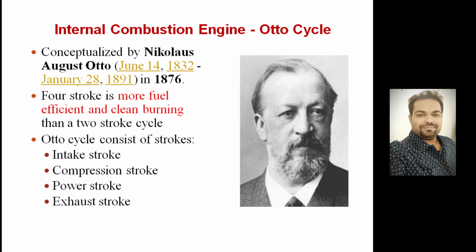The moment your piston is moving down, the piston is connected to the crankshaft with the help of a connecting rod, and the crankshaft will rotate and you will get the mechanical work. Once you have got the mechanical work, the exhaust valve will open. Once the exhaust valve opens, combustible gases will start flowing out of the exhaust valve, and pressure decreases inside the cylinder. Because of that, the piston moves from bottom dead center towards the top dead center. Then the exhaust valve closes, the inlet valve opens, and the cycle repeats.